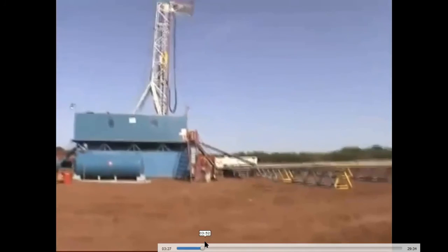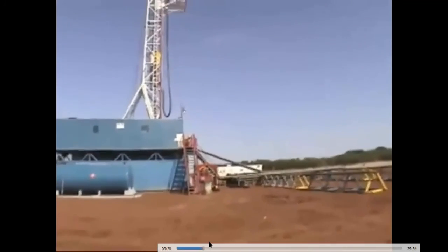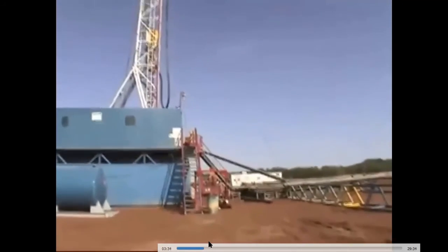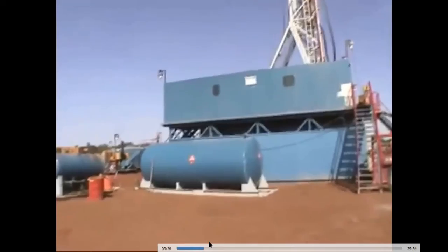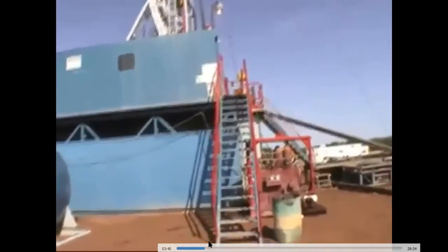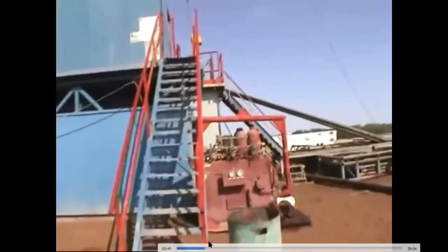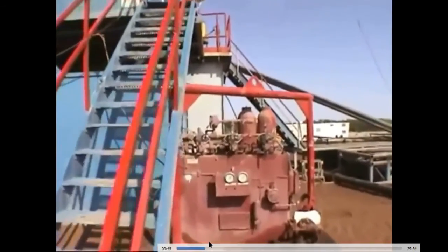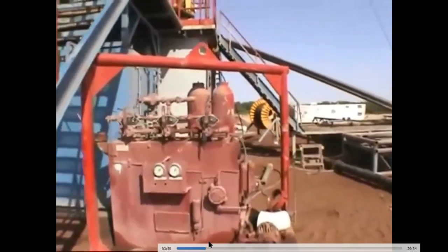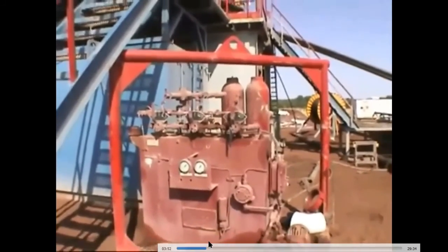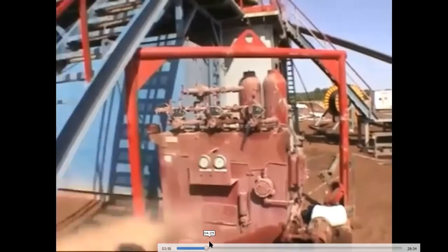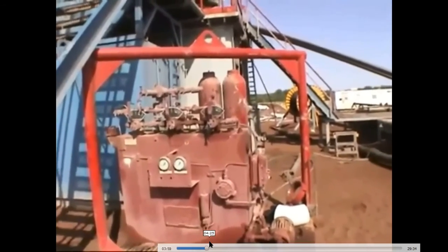Come on up here. Fuel tank. Water storage under here, this tank on bottom. These are the hydraulics that control the blowout preventer. There are rams in the blowout preventer that, in the event of a blowout or something, will close, and these hydraulics, under pressure, seal off the well.